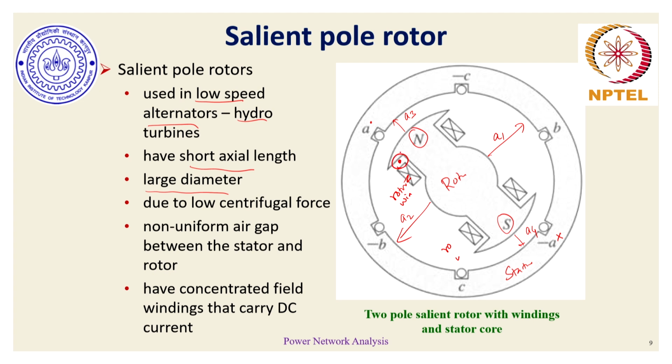So basically, this is the corresponding magnetic flux line. Same for winding 2, it should also carry current out of the plane so that the flux gets additive. Corresponding currents over here are into the plane, as a result of which the corresponding flux lines are in an anti-clockwise direction.